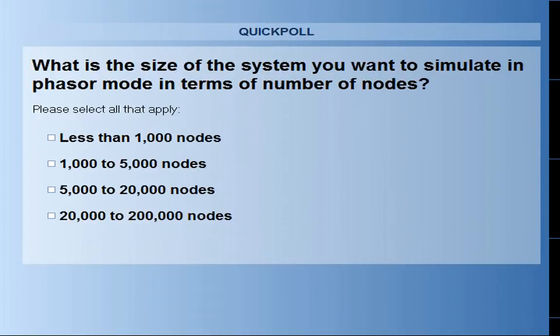And right now, you can see the angle difference between the Arizona area and San Diego is really high. It's above 100 degrees. And here we have the blackout. So we can see when you have the blackout, current goes to 0, and the system separates.